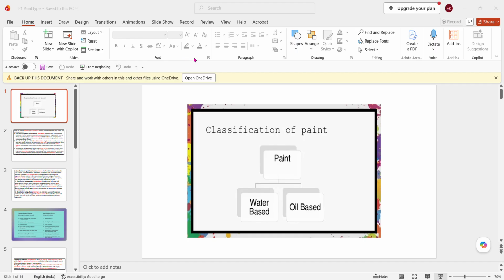Then another one is anti-corrosive paint. You know the purpose of primer. Anti-corrosive paint is engineered with corrosion resistance, with materials like zinc oxide, lead, etc. They will protect the surface from corrosion. Bituminous paint is also like that. It is coal tar or asphalt. It provides a heavy weatherproof, waterproof and alkali resistant black coating for ironwork. If iron is subject to a very corrosive environment, where water sprinkle is there, you can use the bituminous paint.